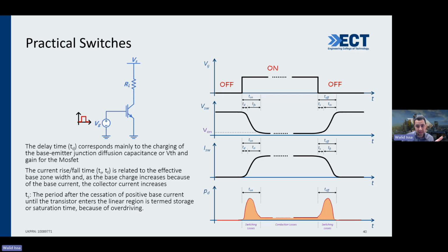They really delay in transition from off to on or on to off because of the structure of the transistor. And these slides here are just for reference. Okay, they show the reasons why the transistor, for example here the IGBT, is turning on slower than what we think, because it has a capacitance inside it, and that capacitor tries to charge before it turns on the transistor.